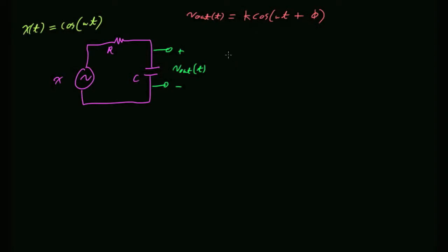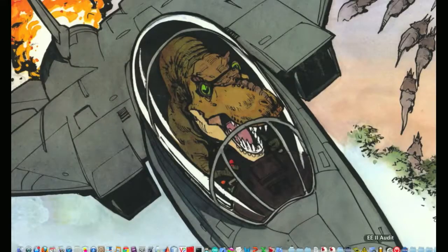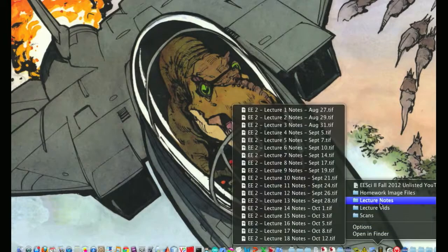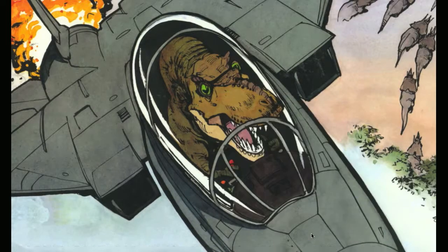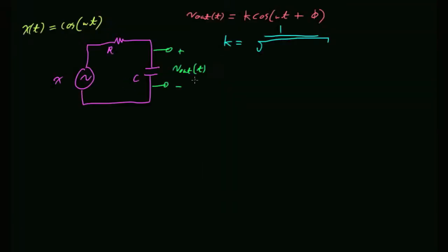And what was the formula we came up with for the magnitude? Can someone help a guy out here? I'm guessing it was 1 over the square root of 1 plus 4 omega squared. Can we express that 4 just in terms of R and C? I think that's right, but if we just wanted to leave it in terms of the resistor and the capacitor values, do we do that? Yeah. Okay, omega RC squared. Yeah, absolutely. So if you happen to know the value of R and C, you plug it in there.